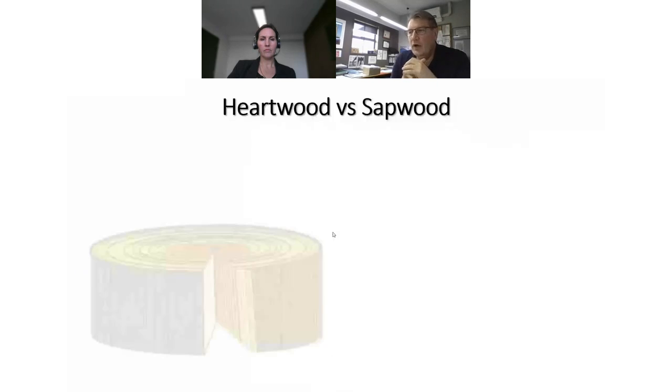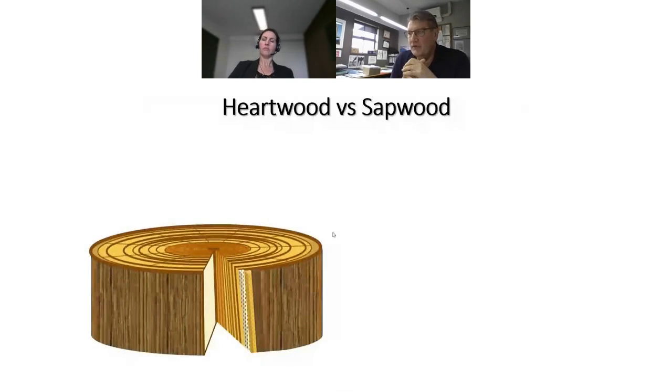Now, I do want to teach you a little bit about heartwood and sapwood, because you will come across it. It does make a difference to the density of any sort of timber, the hardness and penetration or adhesion of coatings, etc. So again, remember that the heartwood is in the core of the tree. It's all gunged up with sap and goo, and there's nothing running up and down it. It's the really dense hard part of the tree.